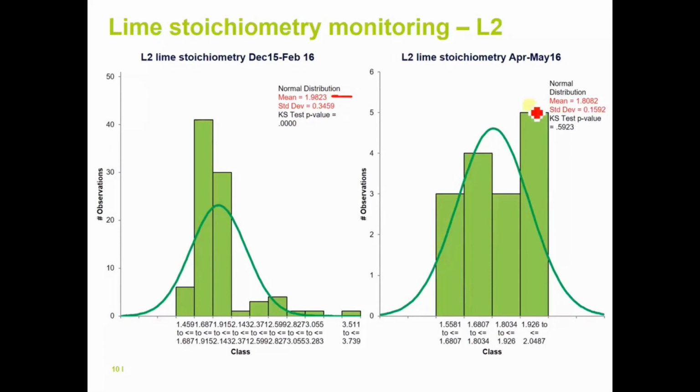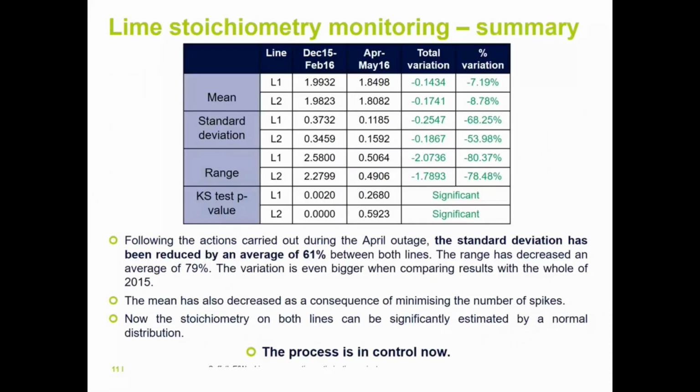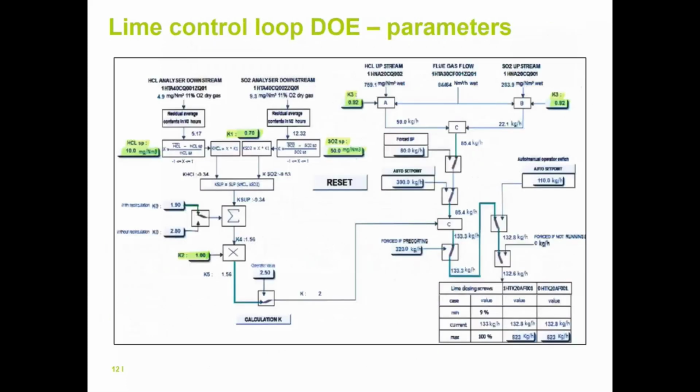Similar thing, look. The mean is sliding down a little bit. Here we had a standard deviation of 0.3 and now we've got a standard deviation of 0.5. So we've taken 2 times the variability out of the process. That's fantastic work. Yeah, that's what you should be doing. Stability always comes first. So that now we've got some stability. There's just a summary of what's going on.